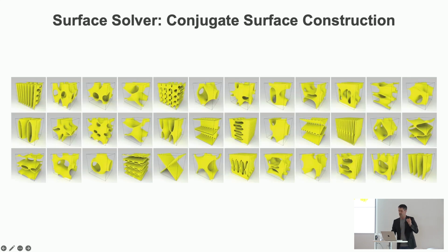And as I mentioned, this is exciting because these TPMS structures have very amazing trade-offs, for example, between stiffness and density, and they approach theoretical upper limits that are there. They're also great for additive manufacturing because they are self-supporting structures. And now by unlocking these TPMS variations, we can suddenly do much more and thoroughly explore this design space of these promising structures.